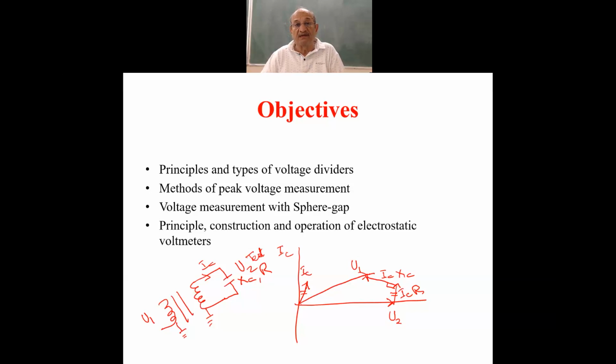That you have to measure from the secondary side. In order to have an exact knowledge of the magnitude of the voltage applied to the test object, which is your aim, you must always measure on the secondary side. And the secondary side voltages, the test voltages, are very, very high. We have already learned about that. So all new and different techniques have to be applied for the measurement of high test voltages.